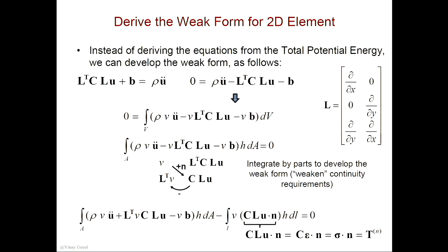So how do we go about this? We have the strong form of the problem. Let's not use Rayleigh-Ritz now. Let's use weak form Galerkin so you can see a different way of doing it. We're going to get the same answer at the end. Put everything on one side of the equation. That's my residual function. Make that residual function orthogonal to V, the weight function.